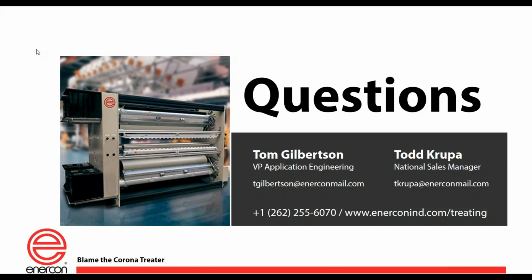Well, remember, folks, what we talked about earlier. What was the key takeaway here? Corona always goes to the path of least electrical resistance. What's water? Is water conductive? You bet. So if in the summertime you have a lot of moisture, the corona's going to want to arc, and it may arc to ground and shut the treater off if it's bad enough. So it is conceivable that if you have a lot of humidity in the summertime, your maintenance load on that treater is going to go up in the summer.